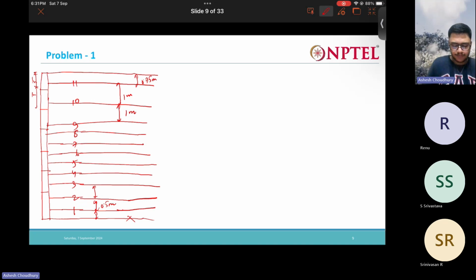One more thing, see, for these top layers, the reinforcement is kind of connected eccentrically to the facing block. If this is the facing block, it is connected here, a little bit slightly down. So there might be some eccentric movement.